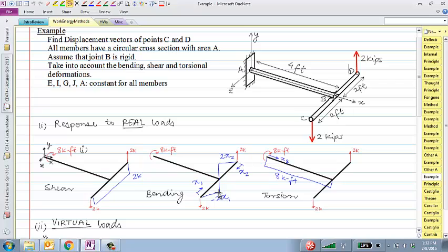When there's a concentrated moment at that location, right? So if there's a concentrated moment at some point in the beam, then there's a jump. Is there a concentrated moment at the center of this beam? Right. So that concentrated moment is coming from the torsion in the rod AB. So whatever bending moment member BC had accrued up until point B, and the same for BD, it jumps because all of that bending moment gets converted to the torsion in member AB. So that was one point.